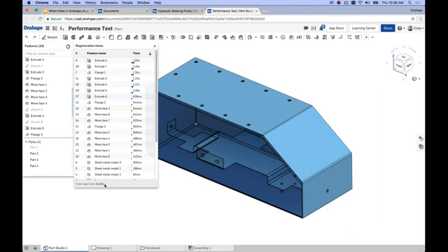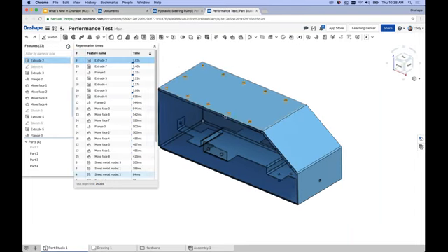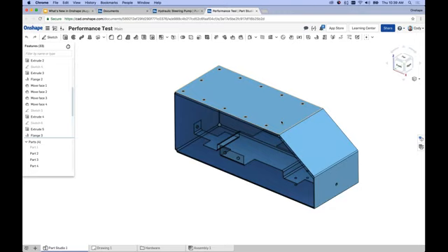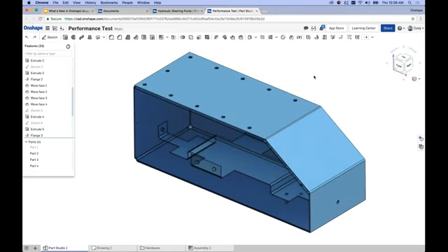This at the very bottom, the total regen time is the number that I'm referring to that we've reduced by quite a bit. And you'll notice it mostly in these cut features where I have cuts going through several sheet metal parts. These have been significantly reduced. And so if you find yourself doing a lot of that, chances are you'll see a pretty significant rebuild time decrease. Right.